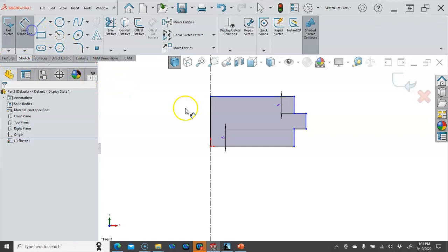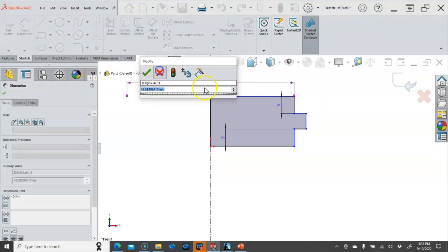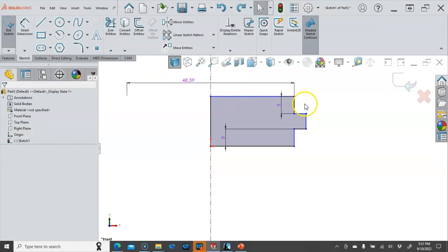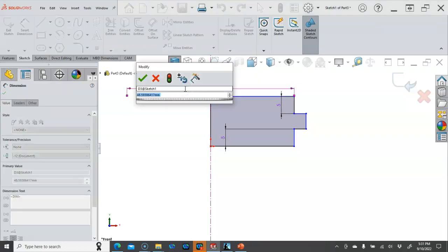So let's get into the dimensions. Let's see, our diameter is 10 and 14. So if I go to the vertical and to the center line, and I did that too quick, so Control Z to get back out of it. All right, so back into the dimension, right click and Smart Dimension, and to the center line. If I stay on this side, I will have the radial dimension, and if we go to the opposite side, diameter. So between the object and the center line is radial. On the opposite side, it will give me the diameter.